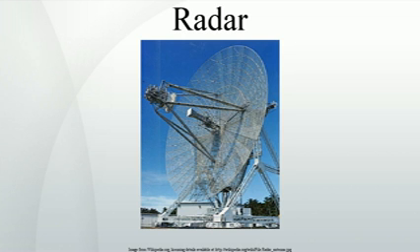These problems can be overcome by incorporating a ground map of the radar's surroundings and eliminating all echoes which appear to originate below ground or above a certain height. Monopulse can be improved by altering the elevation algorithm used at low elevation. In newer air traffic control radar equipment, algorithms are used to identify the false targets by comparing the current pulse returns to those adjacent, as well as calculating return improbabilities.